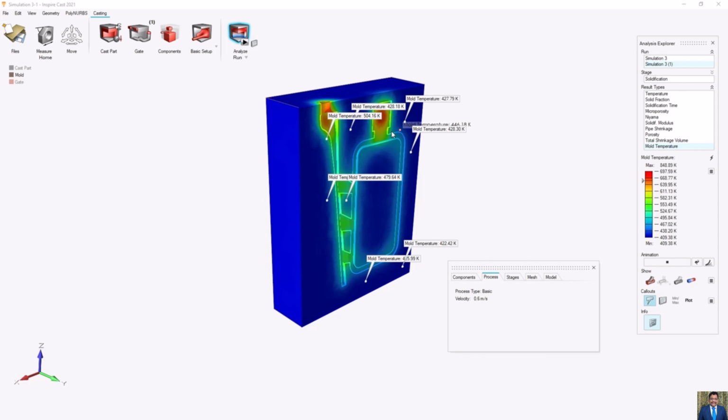Because when aluminium starts to go from liquid to solid, if you go slowly, it's like a refill, and you don't have a problem with shrinkage. It helps a lot for shrinkage, and it's also better for pore. That is one trick when you cast.